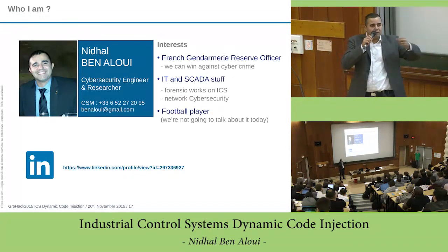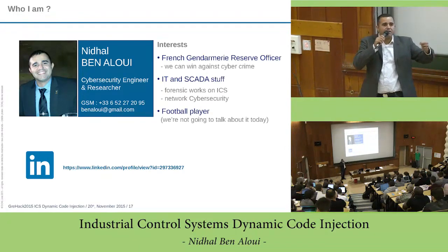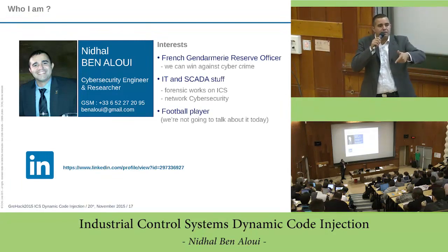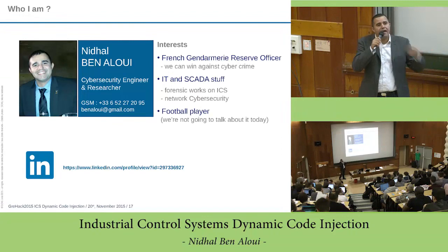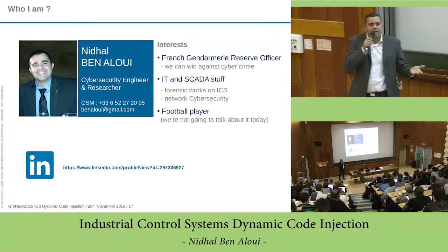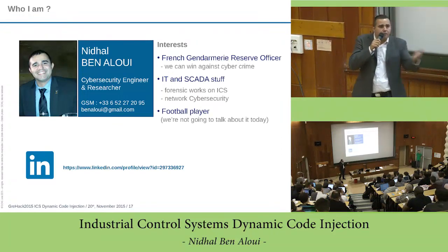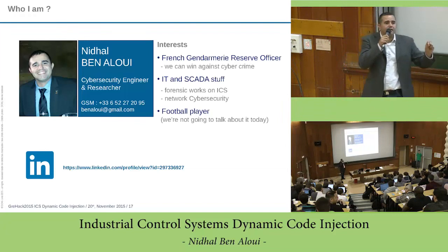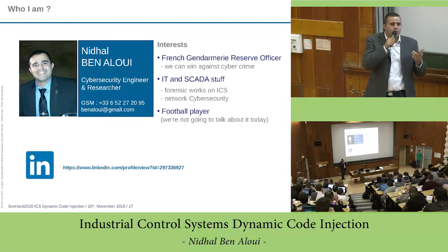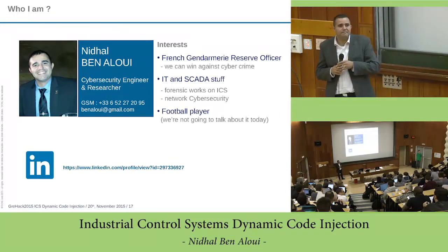In the first 5 packets we have information that means this is a command, and I will inject all the blocks into the PLC. So I can make a rule to detect just these first 5 packets, and then I understand that the next packets are about a full block injection through the PLC. I can make a rule on a specific packet, but a good memory is necessary to detect this on the network. Okay, thank you.